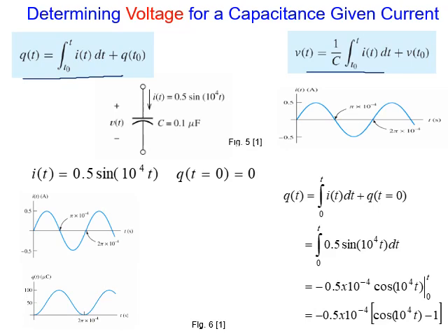Again, don't forget, you have I for the capacitor equal C dV over dt, right? Don't forget this formula. So if the voltage is given to me, as you can see here, I differentiate and multiply by C, see what I got, current. What if the current is given to me? Just go back to this equation, cross multiply and rearrange, you have this formula, which is, rather than differentiation, we will integrate. And then rather than we multiply by C, we divide by C, as you can see here, right?